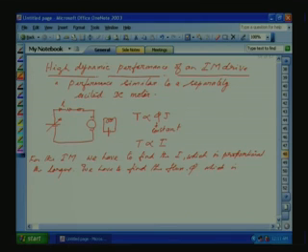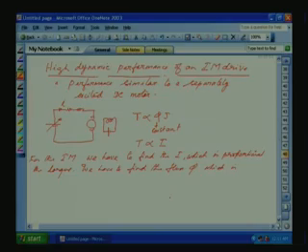For the induction motor, the current coming from the stator is a vector sum of the flux producing component and the torque producing component. We have to keep the flux constant. In the vector diagram, this flux is orthogonal to the torque producing current component.